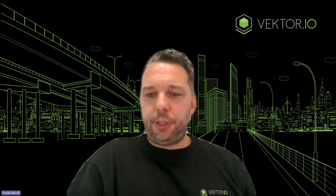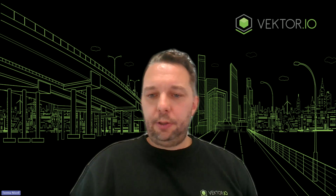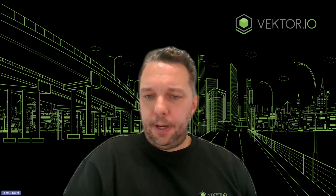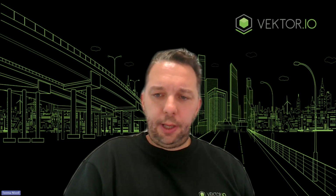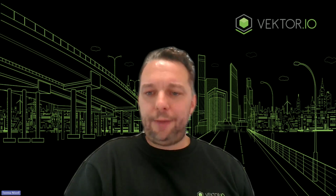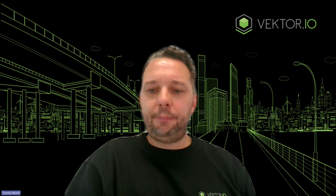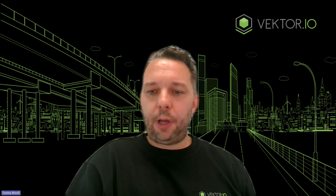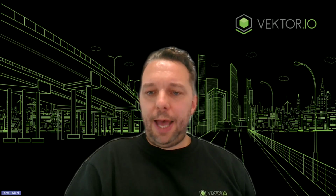And you can get both design models and survey data like point clouds through a DXF. Do you have a 2D map view? How do you represent annotation in 3D? Do you integrate objects such as mileage kilometer points for infrastructure? We have a map view, as you saw in the beginning. We have a sort of 2D mode. We don't have a separate window for 2D and 3D, but you can switch between 2D and 3D mode. And that's why we're avoiding jumping from one view to another. We have mileage kilometer points if you have those alignments that I showed in the cross-section example.